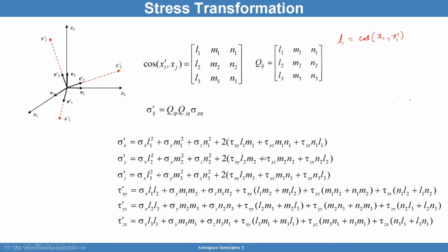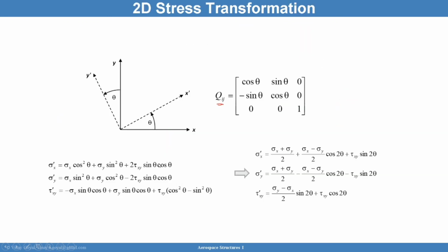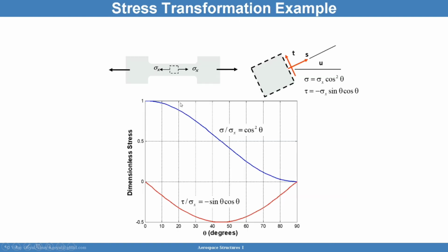All you're left with is these 3 terms which were shown on that page. This should be fairly easy to develop, and these are your 2D stress transformations. In other words, if I know the stresses in the XY coordinate system, I can calculate the stresses in that plane in the new coordinate system.